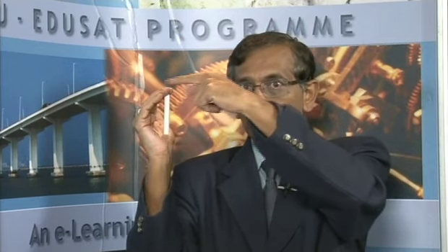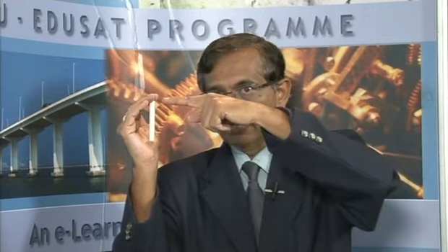So rectangle, area is L into D, and the force will be as per the hydrostatic gamma W, area of this rectangular projection into HC bar. HC bar is the centroid of this rectangle, which is nothing but depth by 2. So from the top we will take d by 2, that will be the answer.